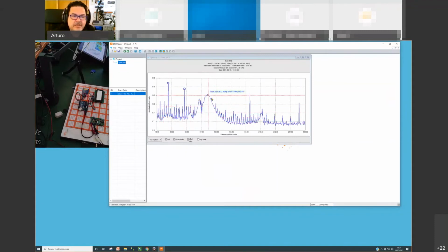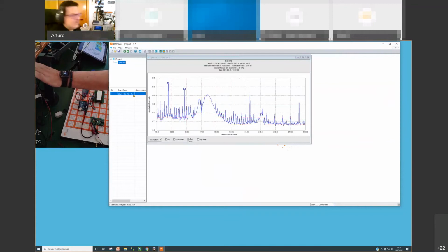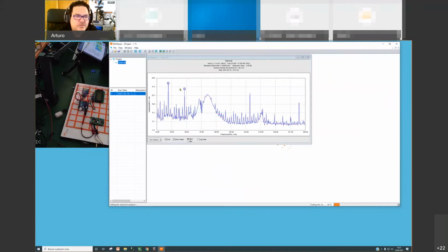Remember, I selected to measure 2 peaks. And this area here is the area of my emissions. The other harmonics, narrow bands, you can see here, are coming from the digital communications that are being processed by the Arduino board, okay? So the idea is, how is the ambient noise in my system? Okay, so we can repeat the measurement, but with the system off. I have switched off the device. I switch on again the scan process. I am measuring with the device under test off. And you will see the ambient noise in my laboratory at this moment.